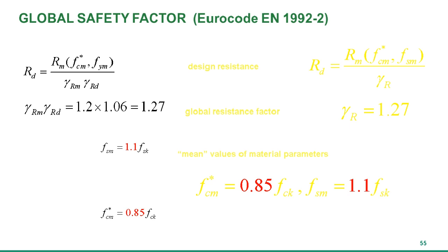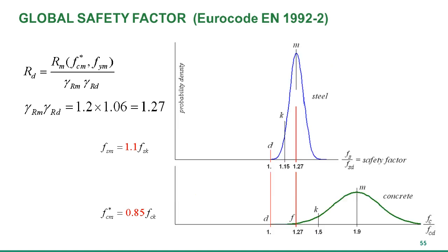Yeah, this is a summary of this Eurocode approach currently in the bridge Eurocode, I think I will skip this one. Basically, this method has an interesting idea that to allow for a single global safety factor, we somehow shift the material parameters. For steel, we use the average values. For concrete, we use somehow reduced values. And this allows us to use a single global safety factor, which otherwise would have to depend on whether the failure is in concrete or in steel.